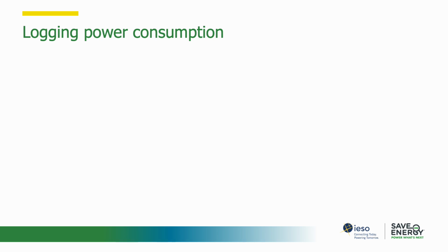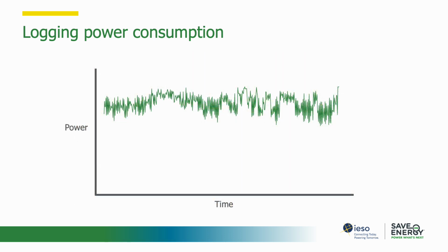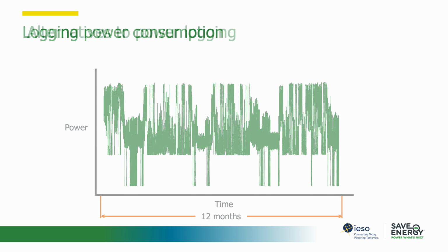The easiest way to measure total energy consumption is to measure and log 3-phase power of the compressor continuously. With those data available, you can easily review historical energy consumption. When establishing your system's profile, a full 12 months of data are ideal to capture all modes of operation and any seasonal variations or production changes.